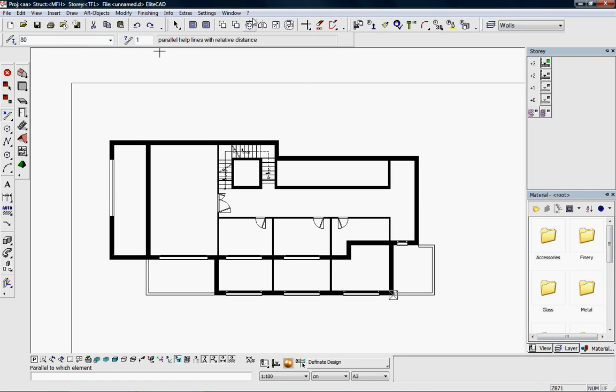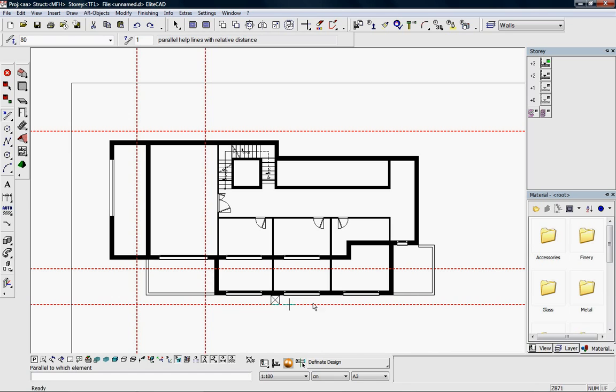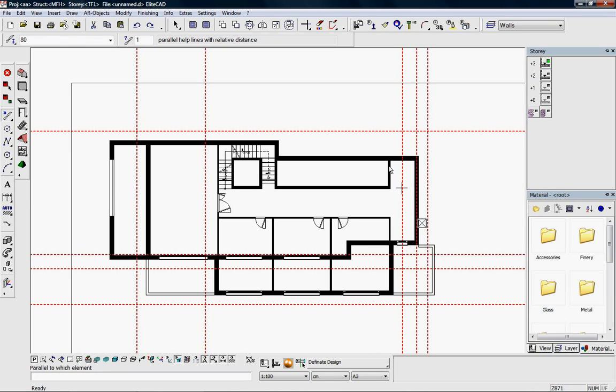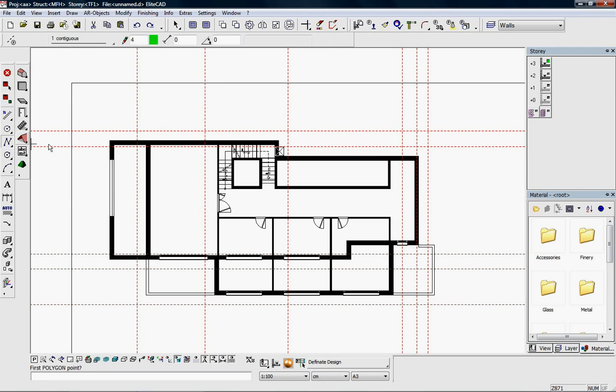Now we would like to create the roof of the building. To create the roof, we set out some guides to position the roof layout, including the roof overhang and contour ridges. We are then able to plot the roof outline by clicking on the guide intersections. We now go around and create the roof perimeter and then select the appropriate roof.